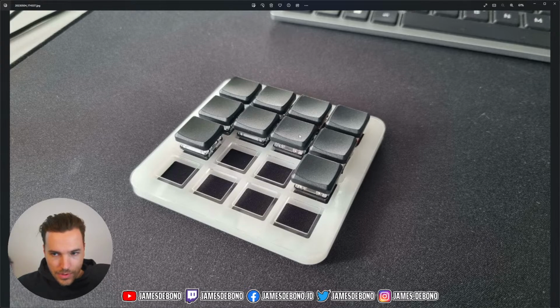Which one of those is the right one to use for a drum machine? Who knows? We're thinking linear makes a bit more sense because if you need to press something in time, like a tap tempo or something, probably you don't want the tactile bump to get in the way because it might slow down the action of pressing, and maybe you don't hit it exactly on time.